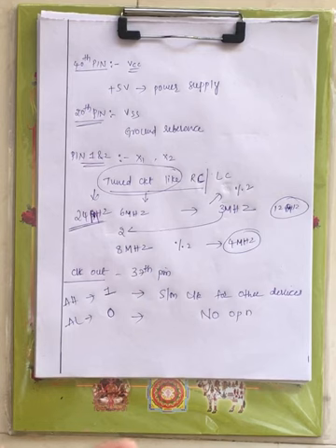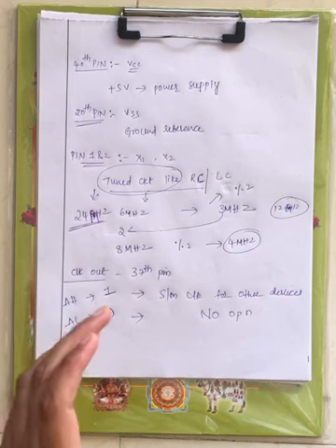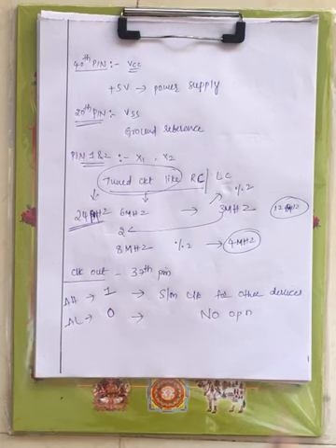The circuit we connect gives the oscillator frequency, the division by 2 is done by the internal clock generator, and that frequency is the operating frequency of the processor. Next you have the clock out signal at the 37th pin.